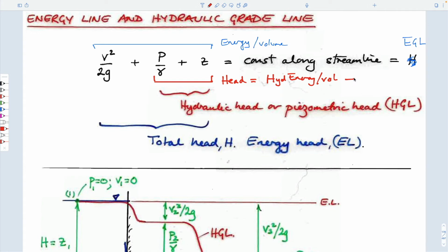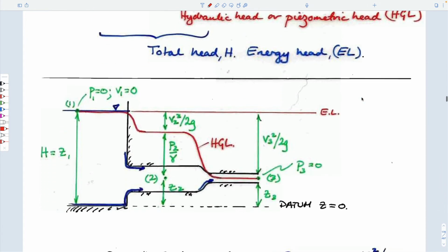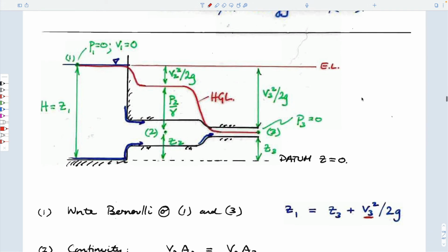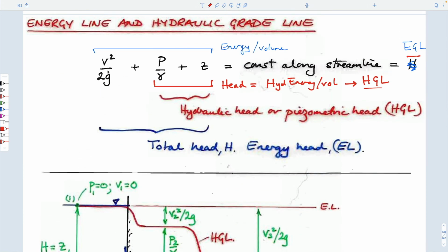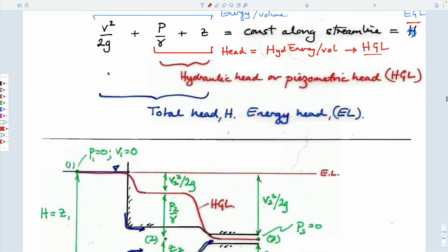But this is what we classify as the hydraulic grade line. And so these two lines are useful to try and understand exactly what the flow is. And so we know that we are constant magnitudes of this total value as we go through a system. So what we're just trading is changes in the magnitudes of these as we go through the system.